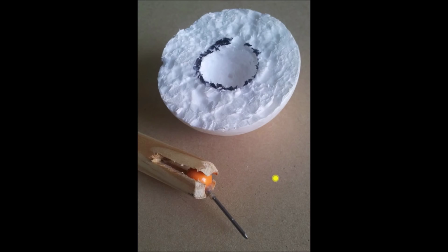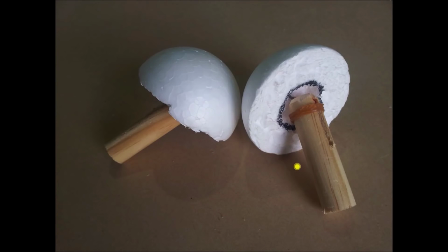So now let's have a look at some of the internal components. The eyeball was made from 65mm foam ball cut in half, slightly hollowed out to allow for the dowel shaft to fit inside. The dowel is 16mm in diameter. The orange bead in the middle there is 12mm in diameter, and from memory I drilled a 10mm hole down inside the dowel and then hollowed out a spherical shape inside using a Dremel. You can see the nail glued through the bead. That is then inserted into the half of the foam ball to create 2 little eye stalks.